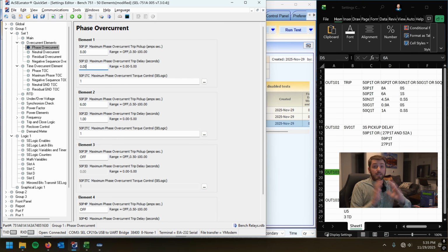thing. It can just basically be used to record any amount of current or do any amount of logic with some current. These don't have to necessarily be protection elements, but sometimes you'll see these used logically in automation systems and things like that. So they'll use a level 3 or a level 4 pickup for some sort of like load shedding logic, for example.